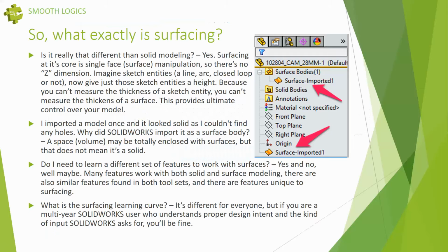If we jump back to PowerPoint here. Imported models will often do it. Or often a good solid body from CATIA or Inventor or Creo or whatever it might be imported into SOLIDWORKS will often get fragmented into a surface. SOLIDWORKS can't define something, or through the translation process, if a solid gets lost, the default behavior is to go to surfaces. Because all of the surfaces that it can recognize will extract out to surfaces, and if there's any holes in it, then it can't be a solid volume, then it just blows it apart to surfacing. And I'm guessing that's what a lot of you have to deal with.